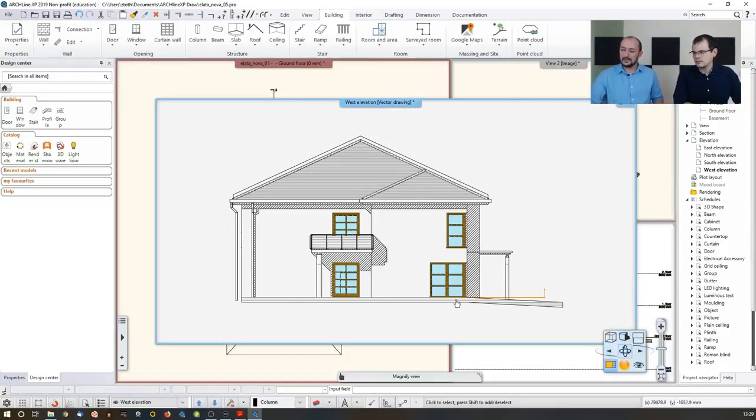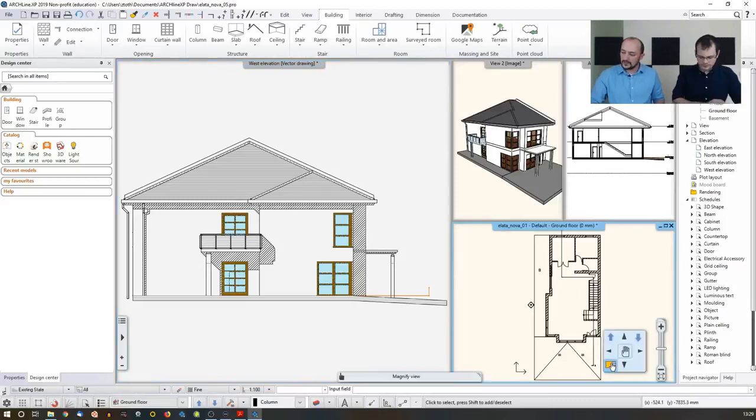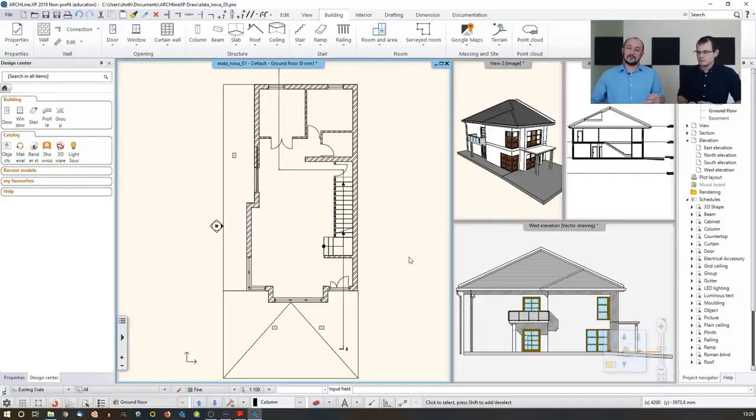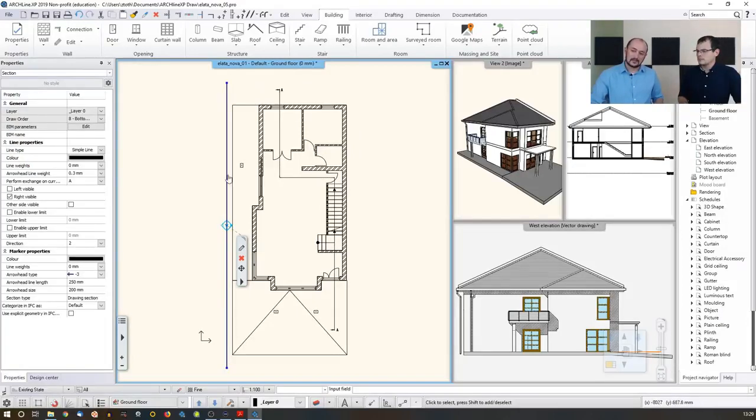So when I click here, the software will organize this content all together with the rest, so I can start working on this one, or I can go back to the drawing, click on this magnify view and start working with that. Now an important thing here with this elevation is that it also has a symbol automatically appearing on the 2D, and it has a certain length. Now it's auto-generated based on the shape and size of our current building, but you can actually customize this length.